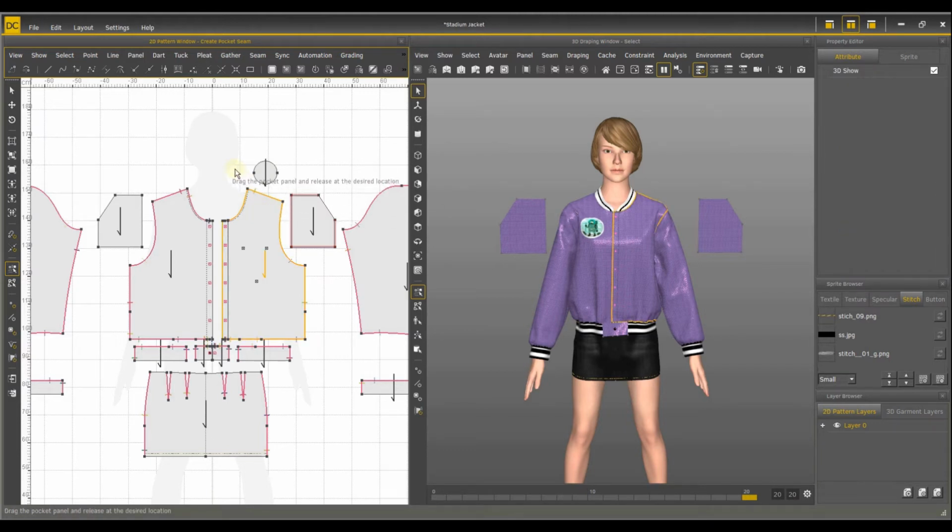Second, select the host panel and drag the Pocket panel to the position marked with the point. Note that you should turn on the Snap button first. It can help you accurately make the 2 points on the different panels completely overlap with each other.